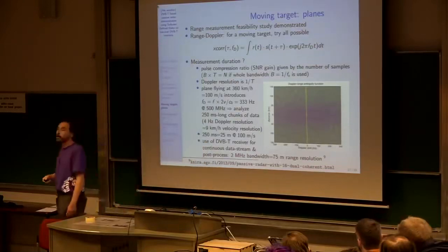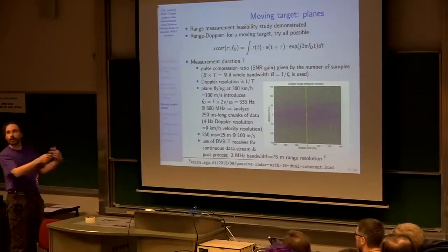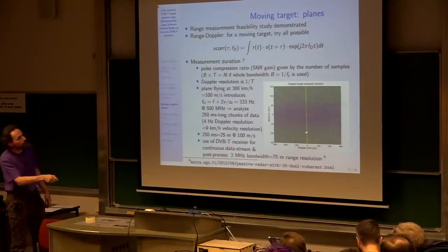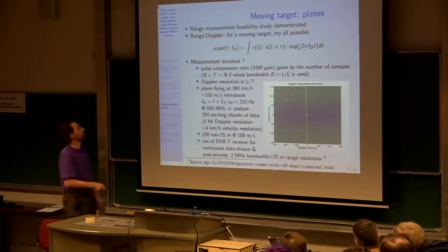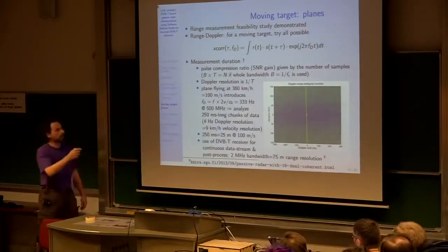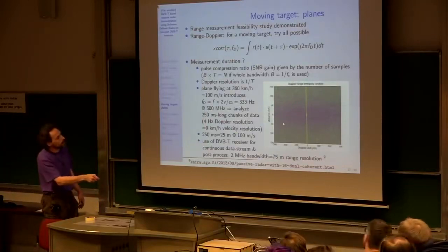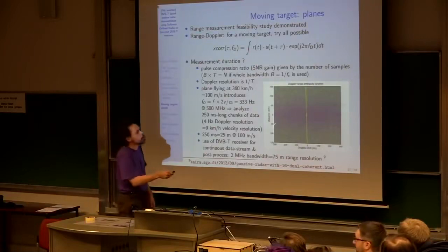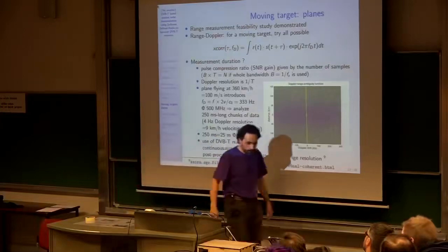So your ambiguity function is actually your autocorrelation when you replace the signal that you collect with the reference signal, and you try to look at all the features of the data that you collect. So you see here, this is the Japanese DVB-T signal, sorry, forgot the name, the Japanese terrestrial broadcast. You have here the zero Doppler, and here you have OFDM features separated by about 210 hertz. You have time-delayed copies of a signal, and these should not be mistaken for targets. These are just features of a signal emitted from the reference signal.